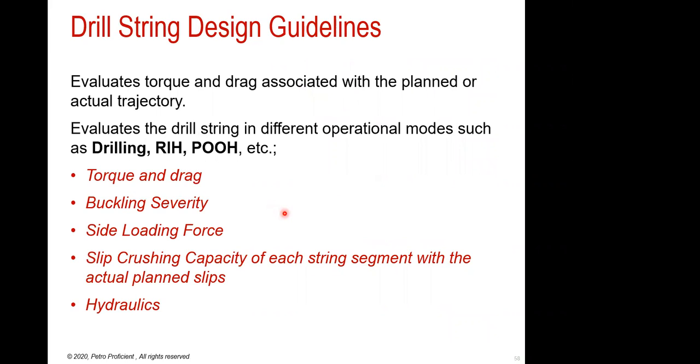Evaluation of torque and drag with the planned or actual trajectory is quite important as a part of the guidelines of drill string design. You have to evaluate torque and drag. You need to calculate buckling severity, side load force, and slip crush of a segment or a pipe string, and then of course hydraulics, where you should be able to clean the hole properly. You should be able to move all the cuttings out when you're circulating, and also make sure that the friction pressure loss is being calculated and is neither too high nor too low to cause an issue. That is an important thing.